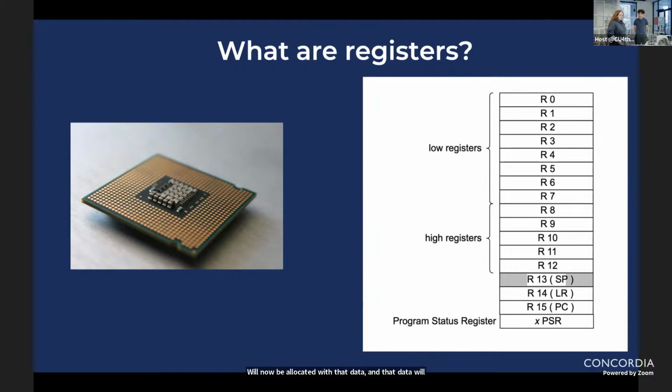So when doing embedded programming, knowing about these registers is necessary because you will often have to directly interact with them. When you're coding in Python or Java, you won't necessarily think about where your data is being stored and what your code is doing to the physical machine. But when you do embedded programming, you might have to directly put numbers in a register that will affect some value. And to know what that value will be doing in that register, we have gigantic documents called data sheets, which are specific to each different kind of board.